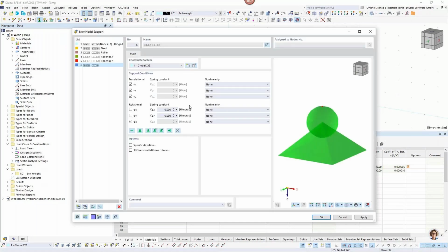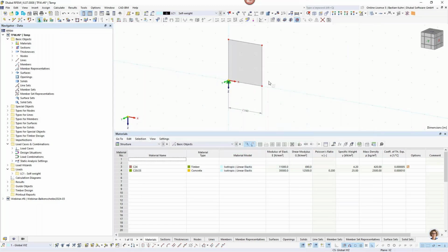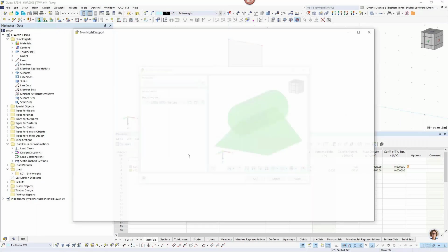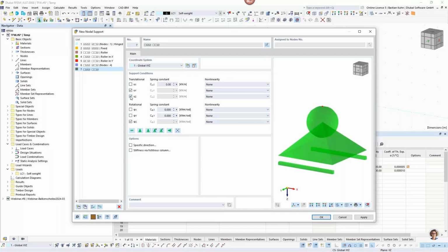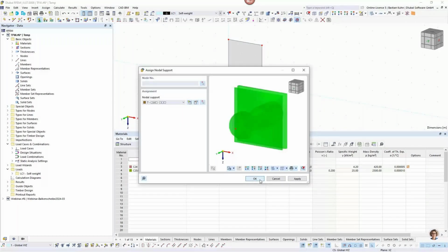In the bigger model that I'm going to do just after this simple model, of course, you would do a complete support underneath the wall. That's for sure. It's just for this first example here. So this one moving, okay, here, and so that it's not flipping outside of the plane in Y direction, I will define the translational degree of freedom in UY direction.